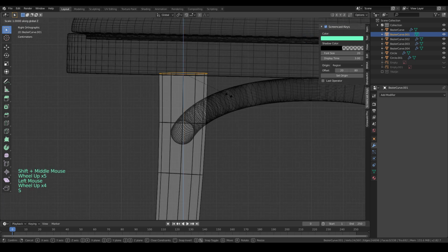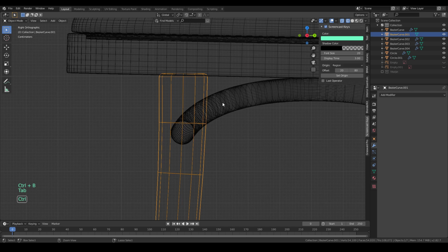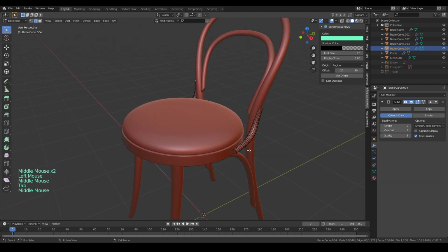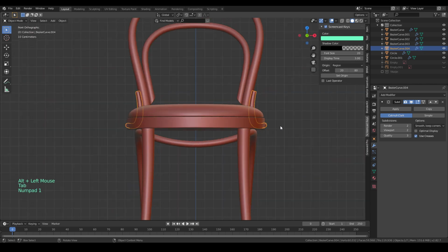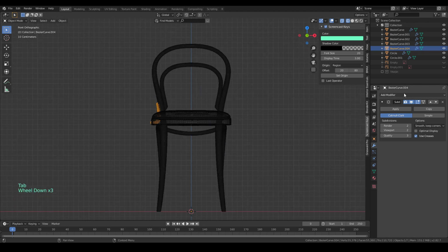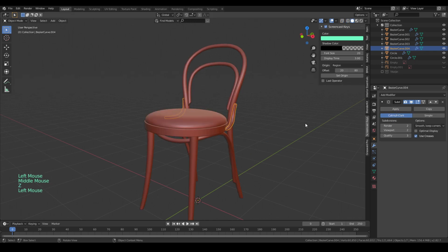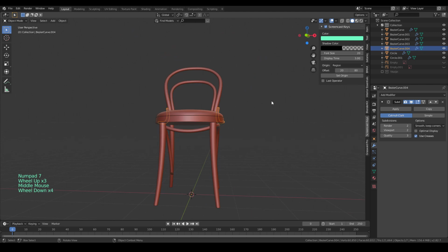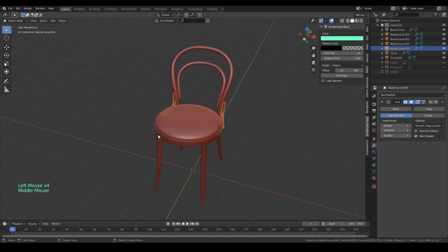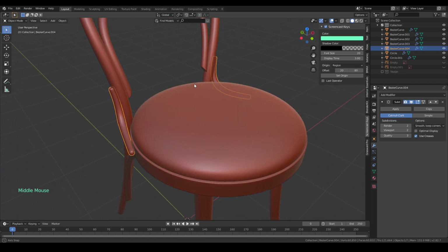And then for the top one, see, scale Z, F, Control B, and another subdivision. So what? This one is not correct. So I'll go to the edit mode and then I'll delete this one by face, and add another mirror modifier. Put it before and then apply it. Okay, the advantage of having the same origin point is you can do the mirror modifier without hesitation. It will correct.